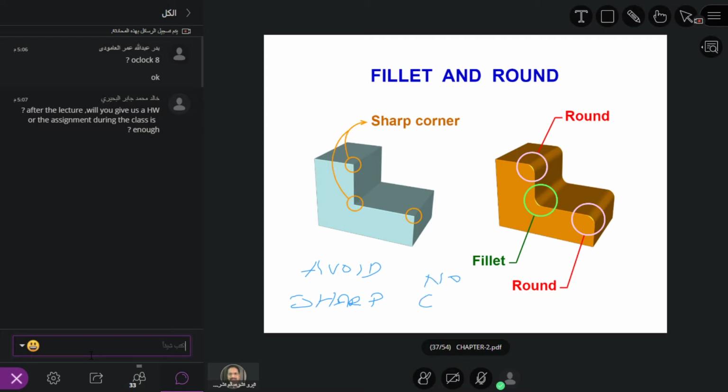No corners or edges should be left sharp, because these sharp edges sometimes could kill, and most of the time hurt, cause wounds. So what we normally do is provide a radius like this shown here, such that accidents could be prevented. In case of an accident, it will also not hurt the end user.